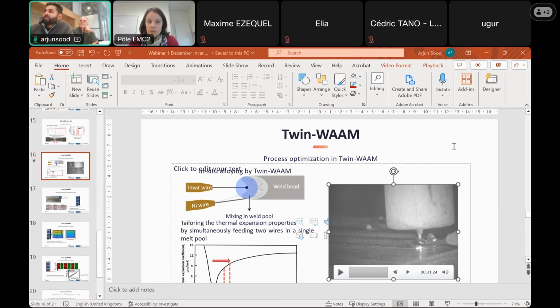And moving on to the next question, which is what are the welding parameters? Mainly, I think you can combine the welding parameters in terms of the heat input. And also, when we are talking about 3D printing, another important parameter is your interpass temperature. Interpass temperature along with the heat input has to be controlled in order to avoid defects. And also, if you have a graded structure, or in the case as we had, in which different alloys were combined, if you have excessive interpass temperatures, there could be a possibility that in the final stage, what you get is a single composition because of diffusion of nickel between low and high areas.